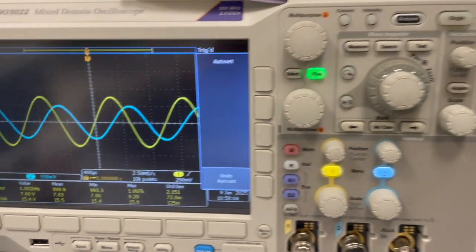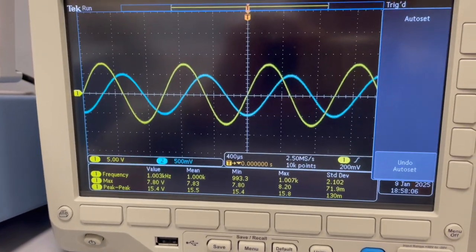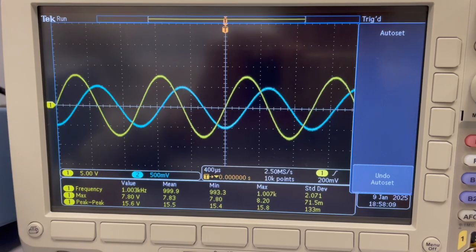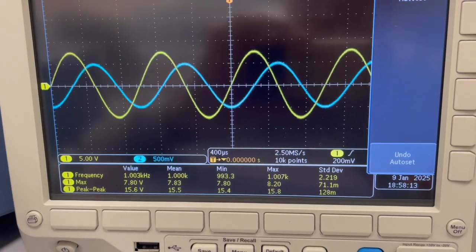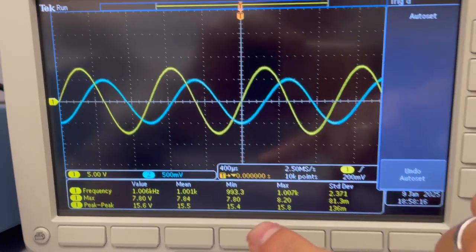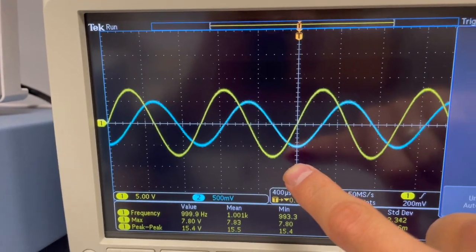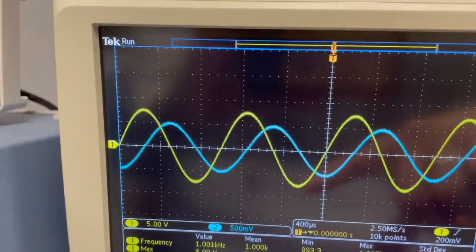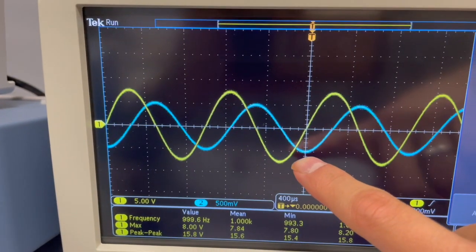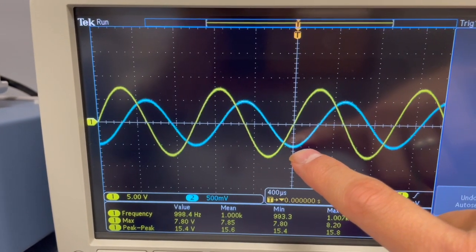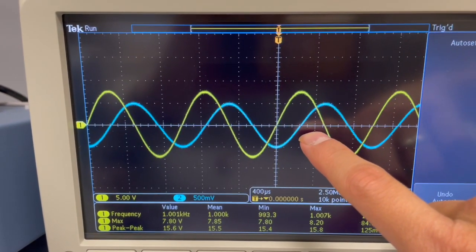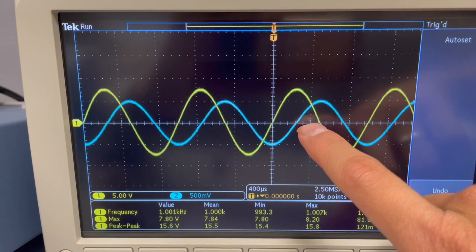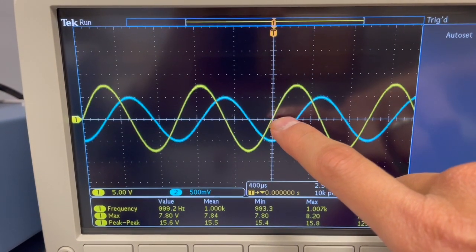Basically why it works like this: as we know, integration is the area under the line of any function. For the input signal, since it's the inverting type, it's going to give the opposite output. We can see the area above the blue line of the input signal is decreasing with time, and up to 0 the area of the output is increasing.